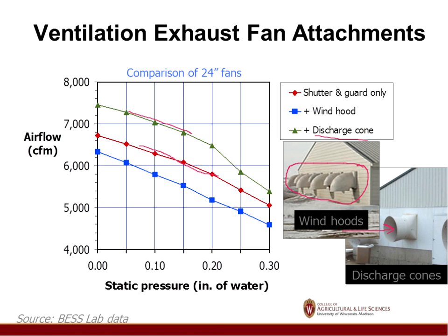One of the issues with these hoods is that it's a deflection. It adds a pressure drop to there. And you can see that in the graph that we've got a big difference here between these. This is in without wind between those. So you're going to pay a price if you put a wind guard on every day because of lower efficiency. And of course, as the static pressure goes up, it increases.